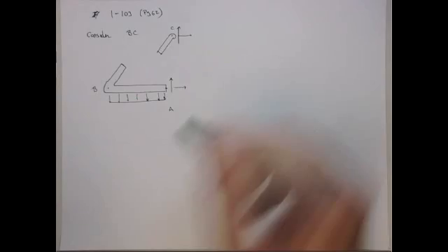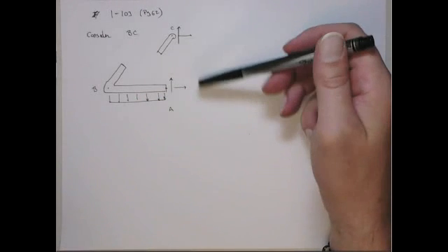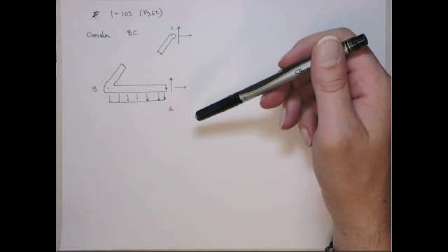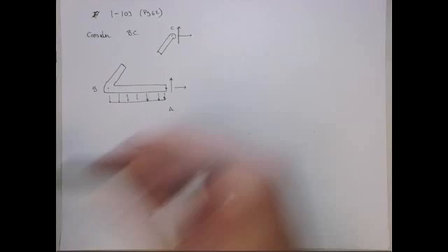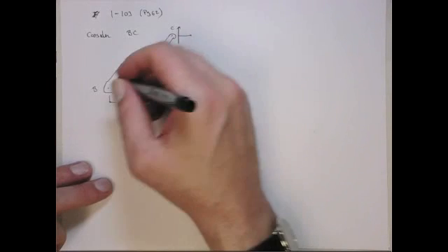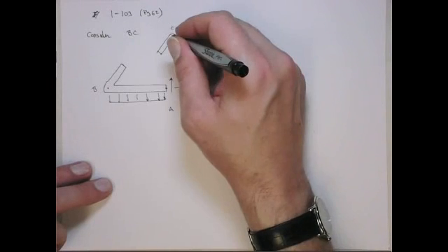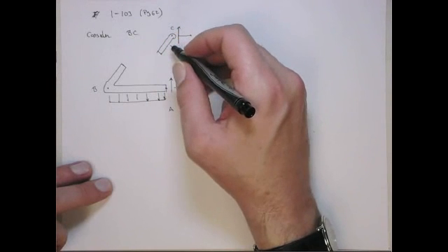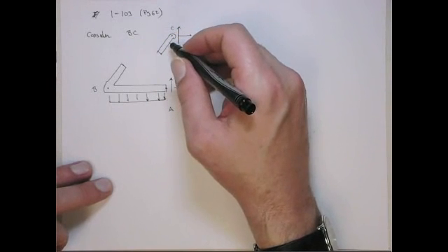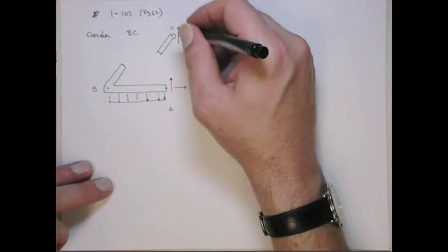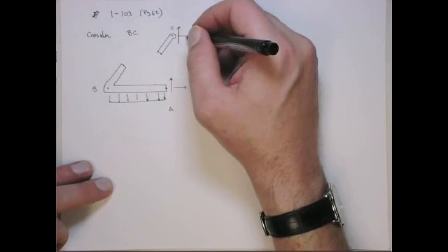Well, if you look at this, you'll say, oh, I have 4 reaction forces, so this is statically indeterminate. But you have to remember, we didn't explicitly go over this in review, but since we're pinned both at B and C, this is a 2-force member, so that means you actually know the direction that this reaction force acts in.